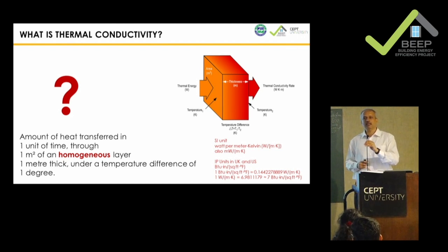You don't look at the conductivity, because if you have brick, the conductivity is different, air conductivity is different, brick conductivity is different. So instead of looking at 3 layers of conductivity and trying to juggle around, we always look at the total overall heat transfer, which is a U value, right?